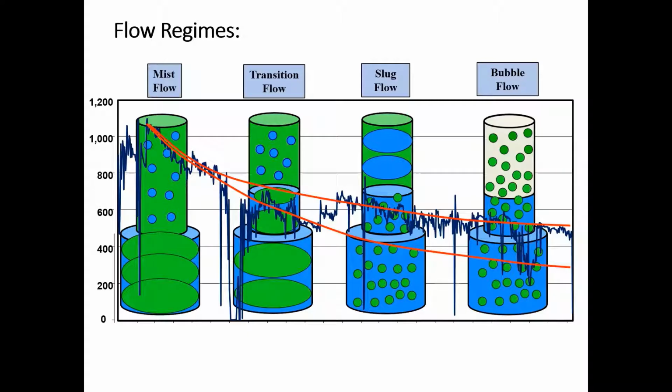The bottom red line represents the natural decline curve of the well, and the line above is the decline curve if plunger lift is introduced. Using a mechanical interface, a plunger, to dewater the well during the natural flowing state can increase production above the decline curve and even extend the life of the well. Plunger lift can also extend the flowing state of the well before introducing other forms of artificial lift like rod lift.